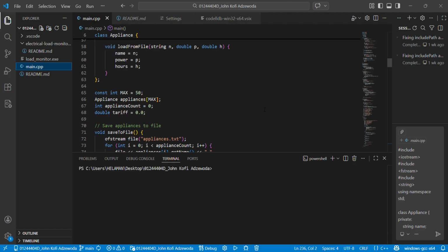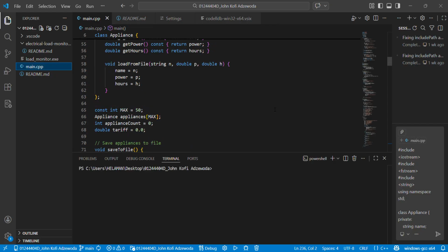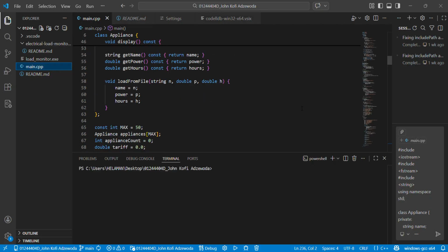We also look at the system output. Example: let's say the TV power is 120 watts, with usage of 5 hours a day. We turn on the TV 5 hours a day. When we want to calculate how much that gives us, how are we going to do the calculation? 120 times 5 divided by 1000. That will give us, please give me 1 minute with the calculation.